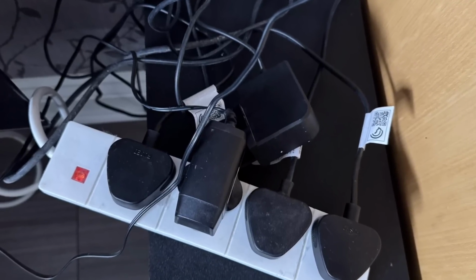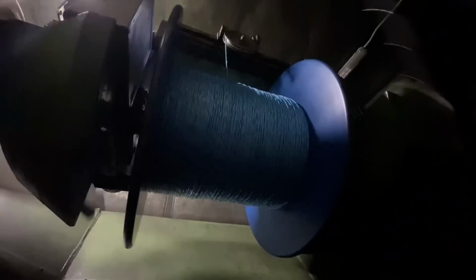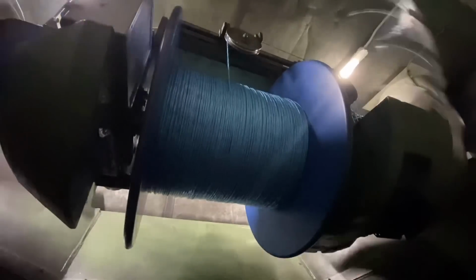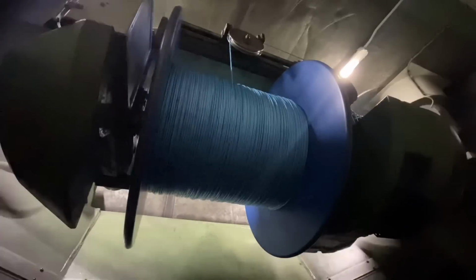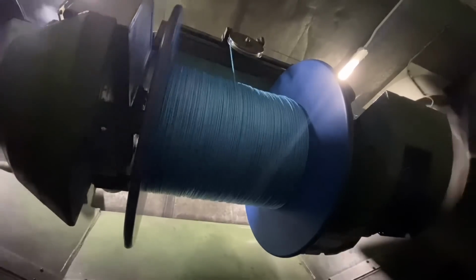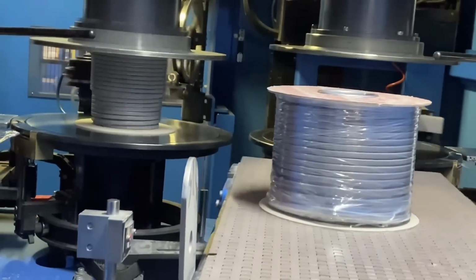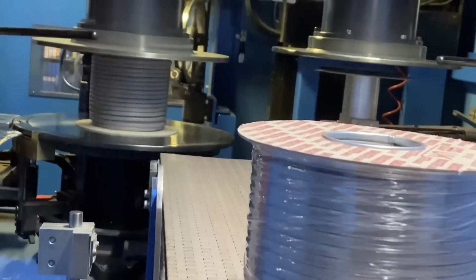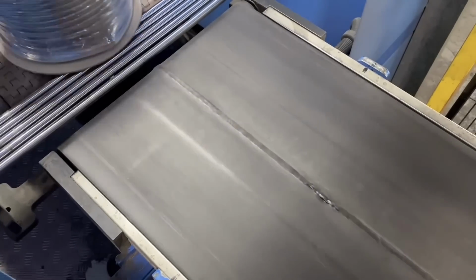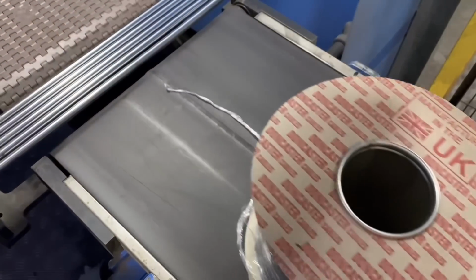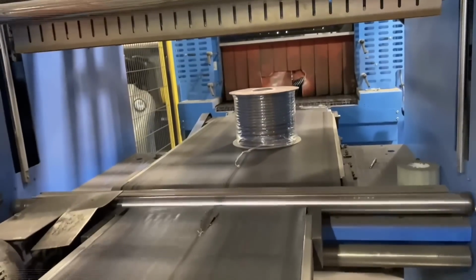It is literally overloaded. The other common way that an overload can occur is when the load is a motor. Rather than just drawing a constant flow of current through itself, a motor will draw more current the harder it has to work. So, for example, if you have a motor driving a conveyor belt, it will draw a certain amount of current to keep that belt moving. But if you start to place more and more weight onto that conveyor belt, the motor will have to work harder and harder to keep the belt moving, and to do that, it will draw more and more current. And if you put too much load on the belt, the motor will draw too much current and damage itself.